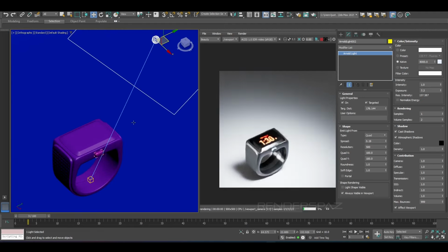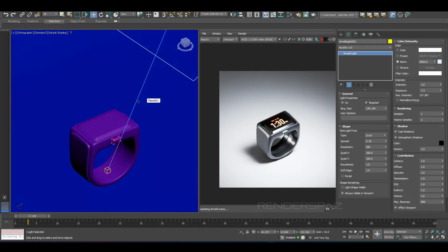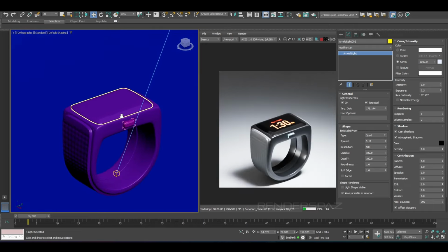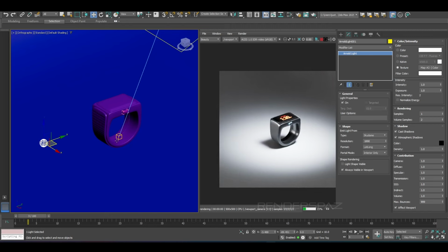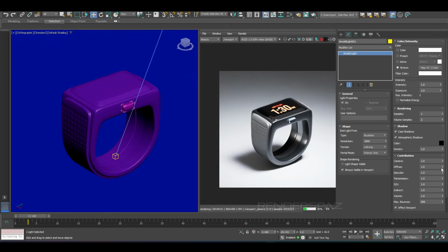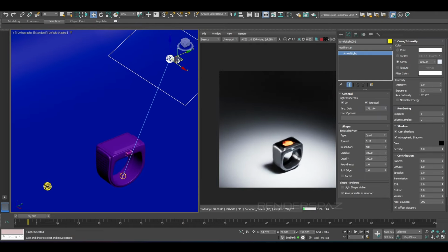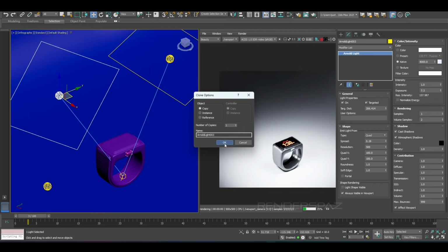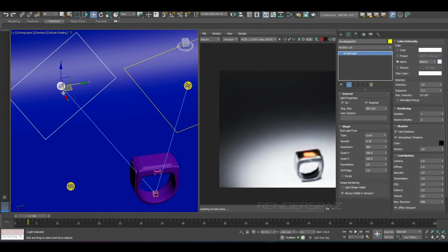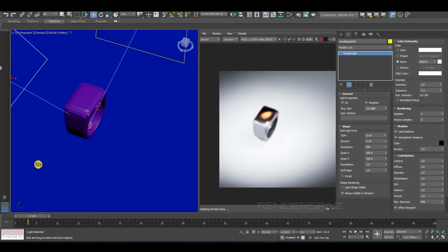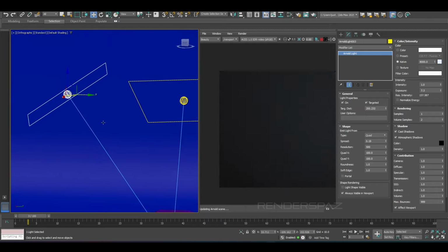And you know what? If I just drag this light over towards more like this, to get more of an angular lighting setup, our shadow's going to kind of stretch that way, which actually doesn't look too bad. Then bring our diffuse down a bit so we're not lighting everything up, but we're keeping our specular. So we bring it down, we lose a lot of those highlights. We'll keep it at about 100%. Already this is looking really dramatic. It's already looking very clean, a nice simple studio setup.